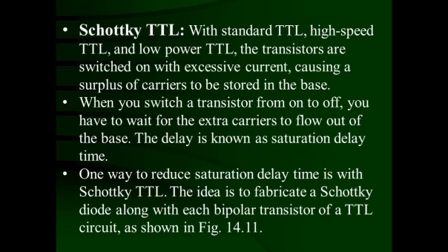And to avoid this saturation delay time, the Schottky diode was introduced. That means the transistor is not allowed to go into hard saturation, but it remains in soft saturation. So it immediately comes out of saturation toward the cutoff Q point, and hence it saves the extra propagation delay time, the saturation delay time, and hence the speed of operation is increased. So this Schottky TTL is very important for speed of operation.